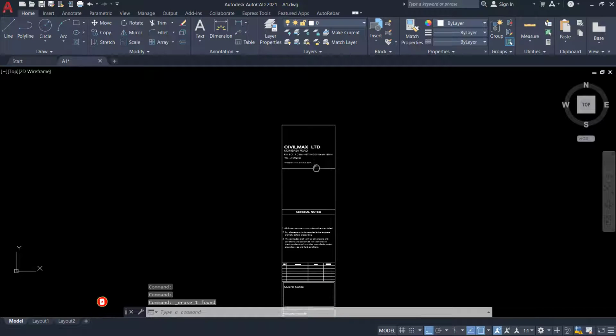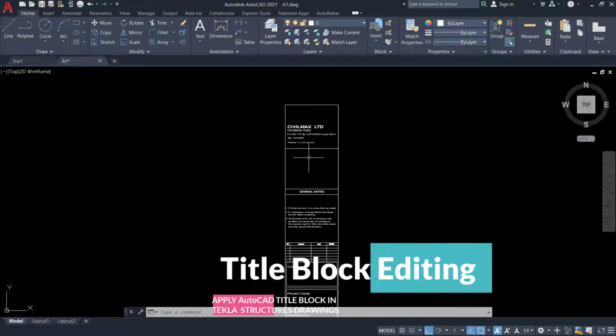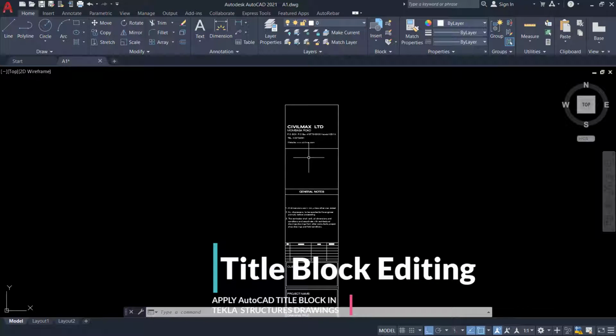Number one, when importing this into Tekla Structures, make sure it is within the Tekla Structures version. I'm using Tekla Structures 2017, and this, if you take a look here, is 2021, and this might not find an entry into Tekla Structures by any means. So I'm going to downscale this to a version slightly below Tekla Structures 2017. It can be 2017 or below.